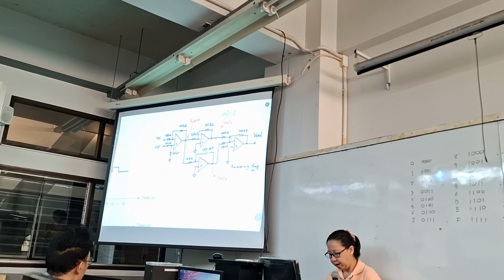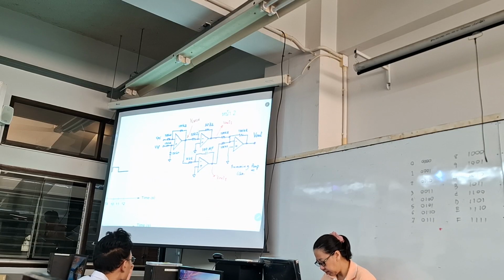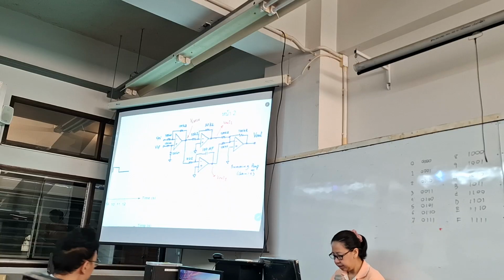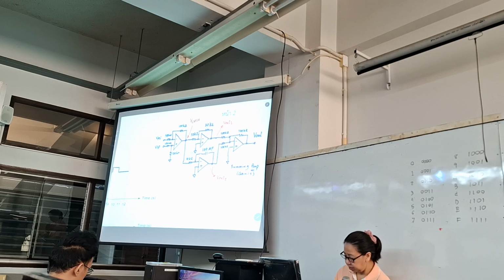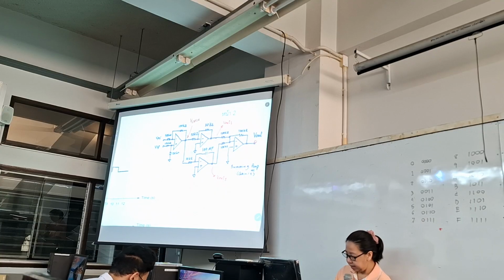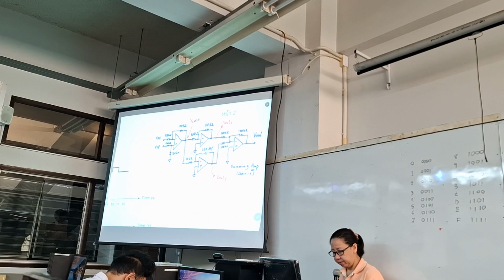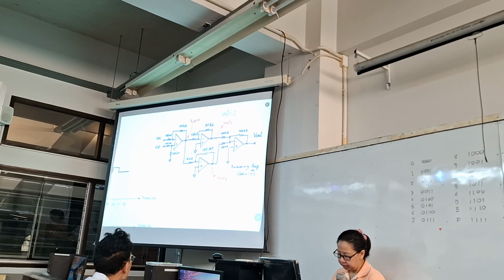Then I can define the gain as equal to 1. So we just combine the effects of the P controller and the I controller, and you will get one output. This is the output from the controller that you will send to the drive to control your actuator to move in the percent that you need, from 0% to 100%.